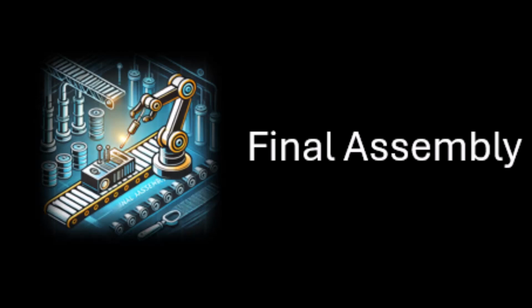And then you have final assembly, which, if it's a simple product like this, is one PCB that gets tested. Usually if these things are in series production, then you define an automated testing strategy. You can't test 100,000 PCBs by hand. That would take forever. You would define some test automation to do this for you. That's a separate topic, which we could touch upon in a future video.